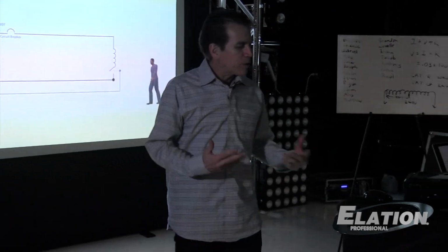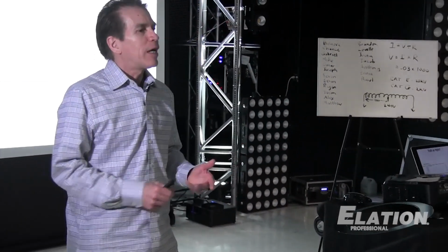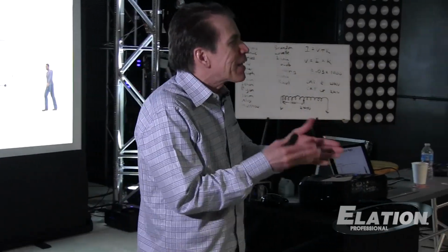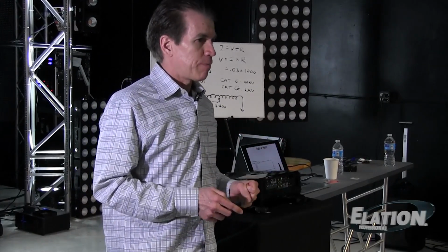But sometimes you have no control over that because it's induced current. It's coupled magnetically because of the proximity of the grounding conductor with a high current carrying conductor, and it just causes current to flow in it.